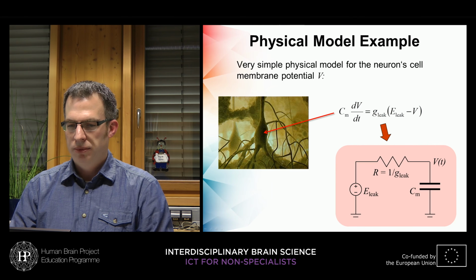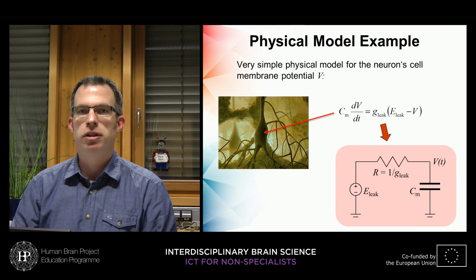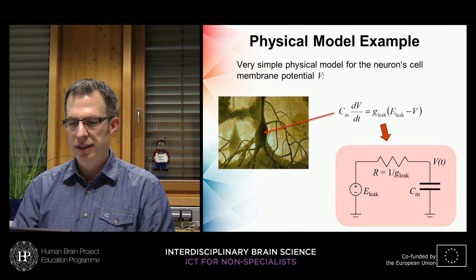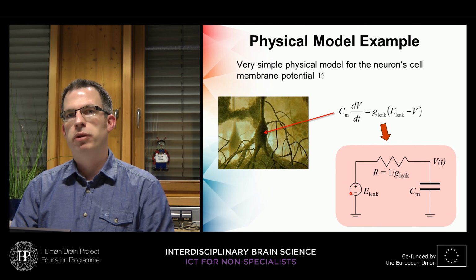And this is realizable, that's the leak term of the leaky integrate-and-fire model, a very basic differential equation. And this can already be implemented by such a simple circuit down here. We have the membrane capacitance as a central element. We have a conductance, that's a resistor up here. And this is just connecting to a voltage source, providing our leakage reversal potential E leak.